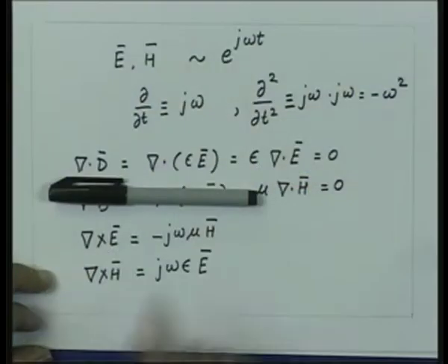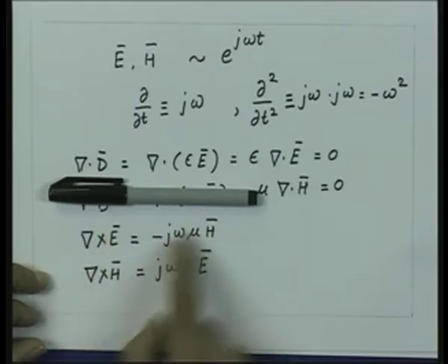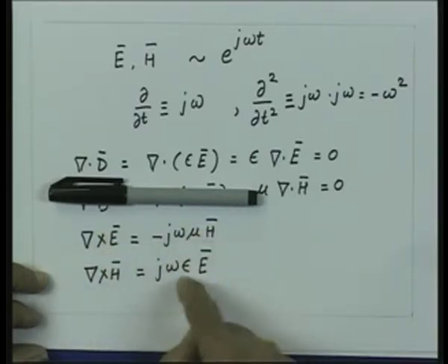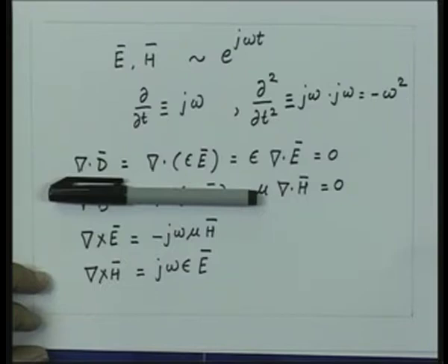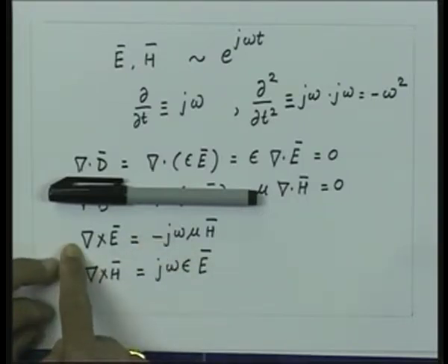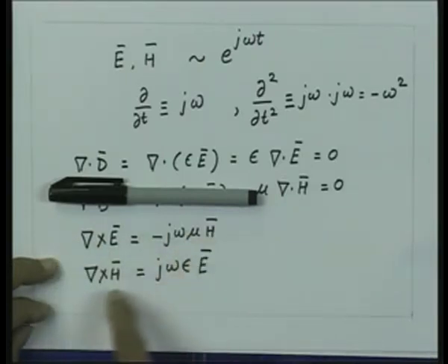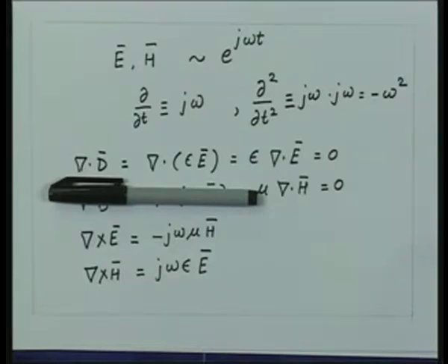Also, as we had noted at that time when we were analyzing transmission lines, these equations are coupled equations. So here electric field is related to magnetic field and magnetic field is related to electric field. So if you want a solution for the electric and magnetic fields, we have to decouple these equations. And if you recall, in the case of transmission lines, we had done that by taking the derivative of each of these equations and substituting from the other equation, so we could decouple the equations.